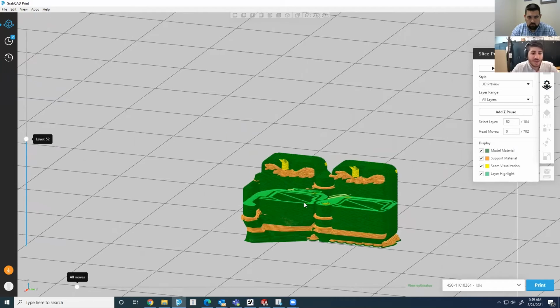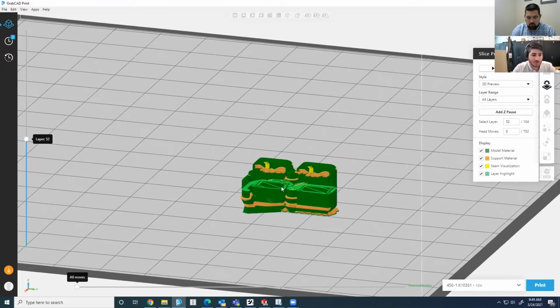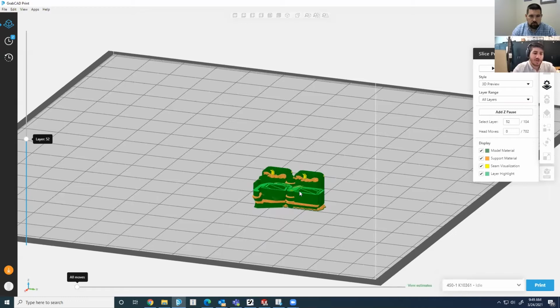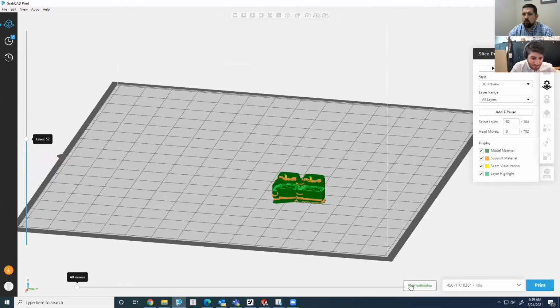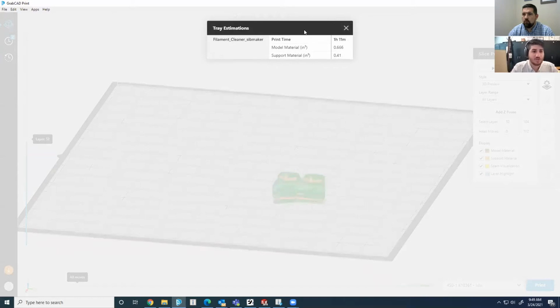And that way it's not switching, because every time it needs to switch to sacrificial support material, the head needs to move over to its home, purge that head of the support that is sitting in the head, and then move over, draw out the support, move over, purge out the model material, and then resume printing the model. It needs to do that for every layer. So you can see we actually gained time.